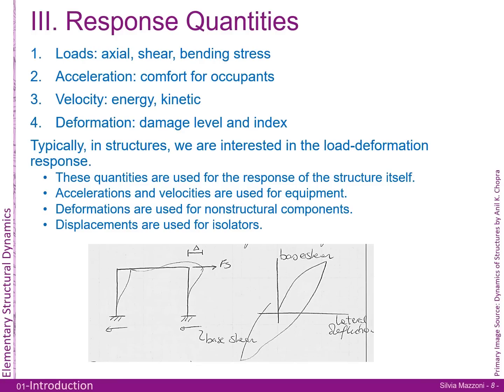Accelerations, more than for your structure, are actually meant for the comfort of your occupants. You don't want to get your occupants seasick during a windstorm, or even just basic wind in a really tall building. The velocity component is also part of the response of the components of your buildings, but it's also very much a measure of how much energy is in the system. And deformations is something that we're interested in, especially now that we're doing ductile design. We want to estimate what the damage levels are and what our damage index is. Where are we with respect to the deformation capacity of your frames? So typically in structures, we're interested in the load deformation response, which is what you see here.